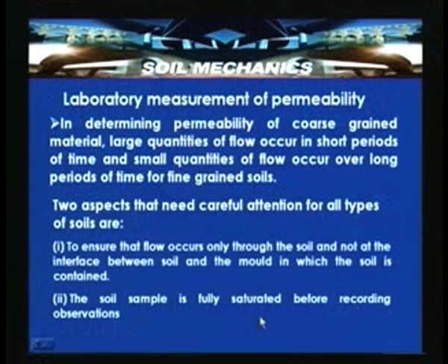So, two aspects that need careful attention for all types of soils are, the first aspect is to ensure that the flow occurs only through the soil, not at the interface between the soil and the mould in which the soil is contained during the permeability test. And the second is that the soil sample is fully saturated before recording observations. So, this has to be ensured. The importance of saturation of the sample is very much required.